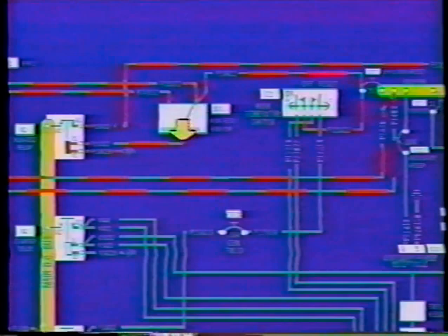Follow the wire leaving that bus through the generator and bus reset circuit breaker. Continue the trace to the non-essential bus switch. With the switch placed in the manual position, controlling power is placed on the non-essential bus relay at X1.